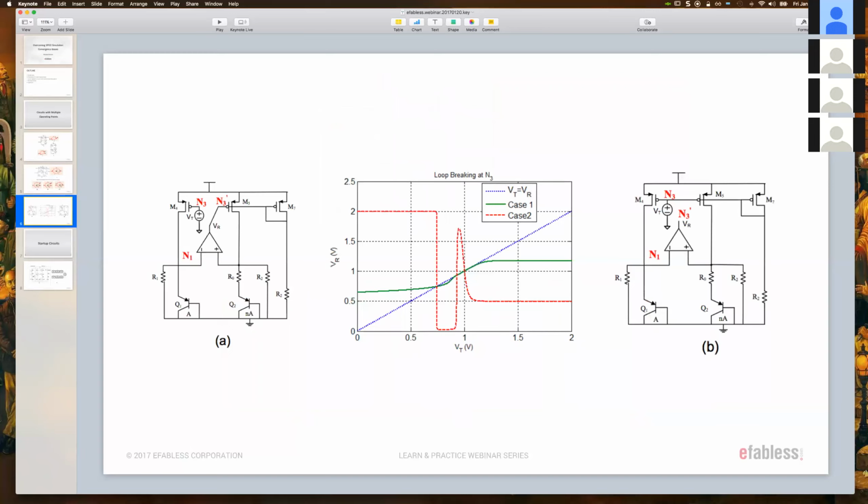Depending on these, there's no single bullet answer for that, but there are rules, and I learned that from one of my colleagues here also. Which loop you choose to break depends on the mathematical accuracy that you want. Usually you try to break it in a place where the next stage would be a lower gain, so that the sensitivity is low, so you don't have to apply very small numbers for the sweeps, and you'll be able to reach accuracy.